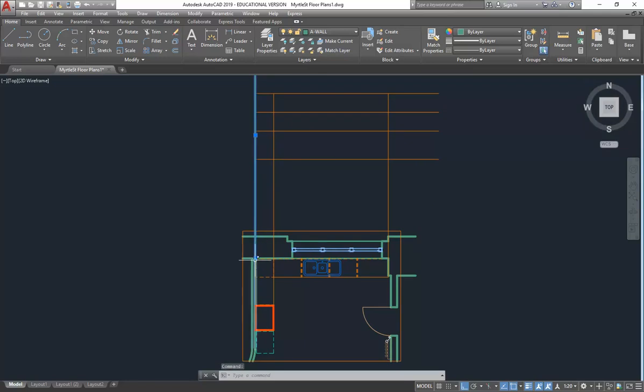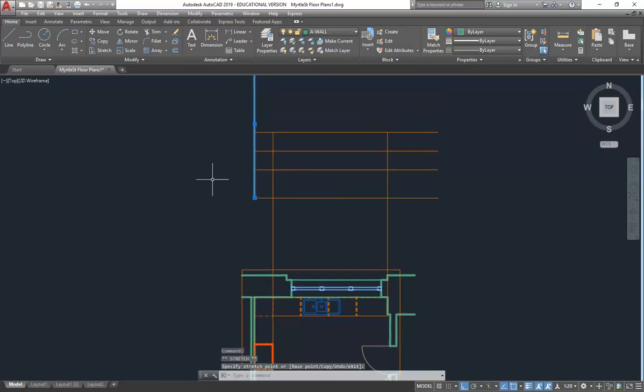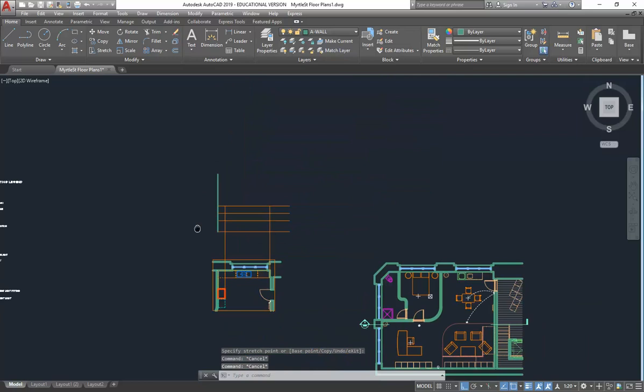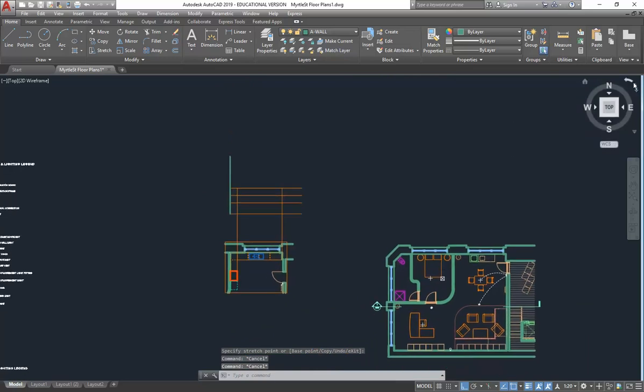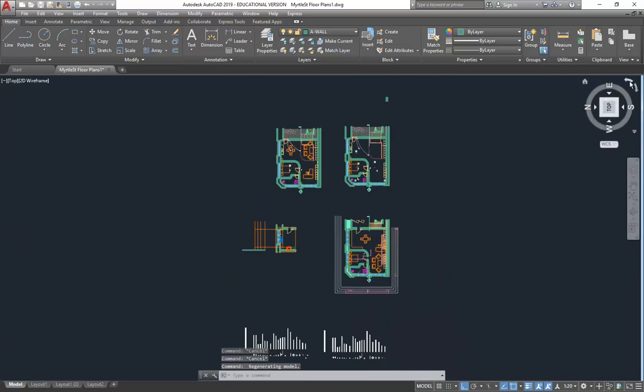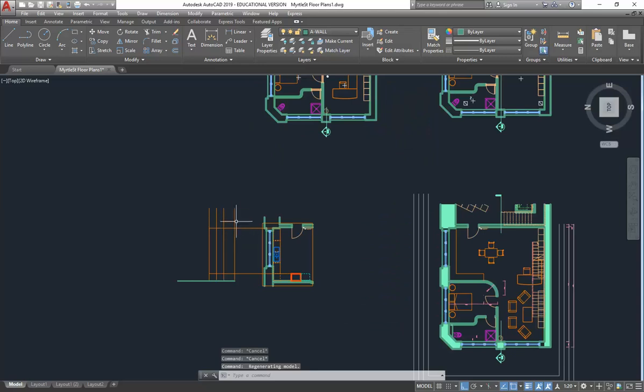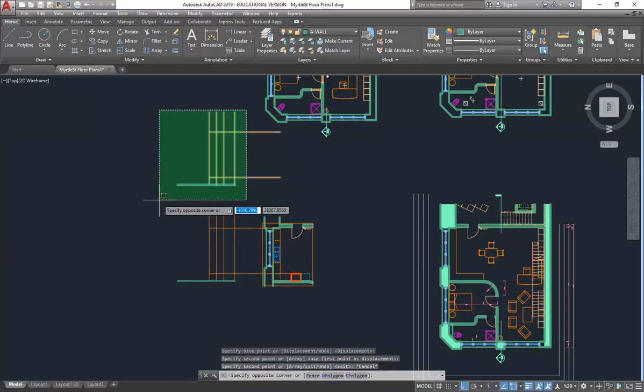So that's enough for me to start setting up most of the views, but in fact what I might do is just start to set up one of the other elevations. Now, you can project with polylines and rectangles to have these lines automatically project across with the same heights. But I think it's probably just as easy to copy these things and then rotate them.